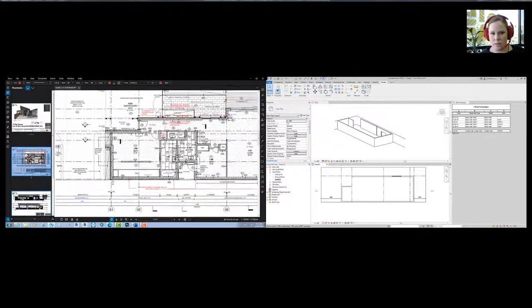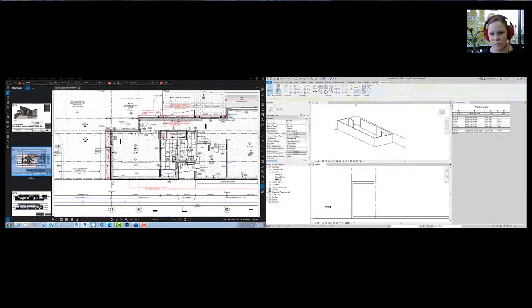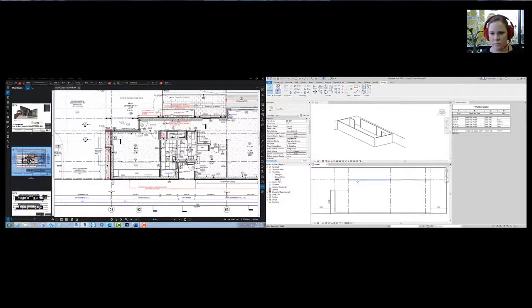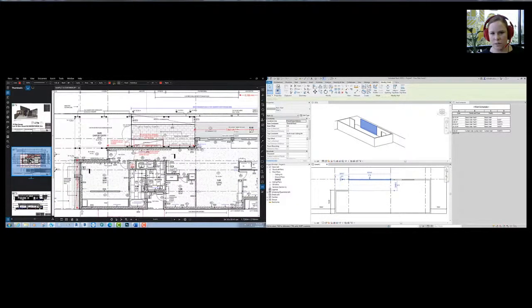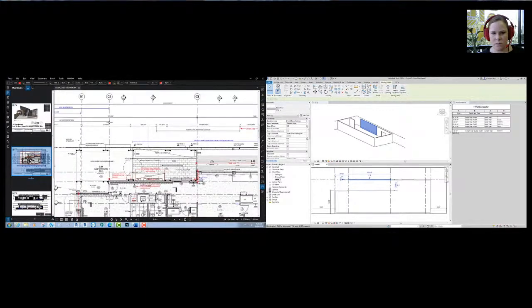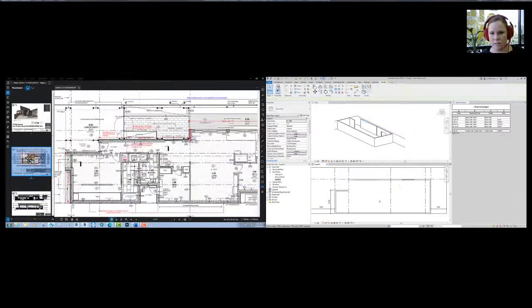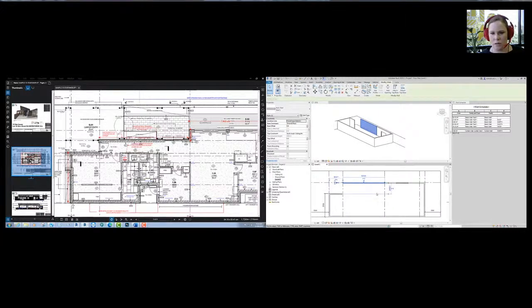Okay, and then in this instance we need to also work out what the other offset is, so you'll see that now. So what we're going to do is measure in Bluebeam roughly how tall this is. Okay, so I'm going to use the dimension tool, a little bit more exact in this instance. Okay, and then this wall also needs to come down. You can see that there's a little recess there, and in this point just here. So I'm going to put a measurement there so I know how to offset that one, and just make sure all the padlocks are taken off.